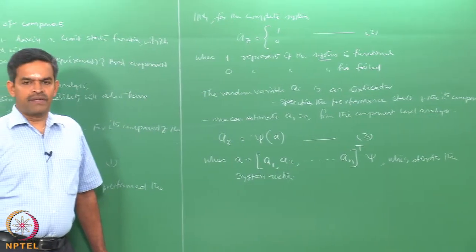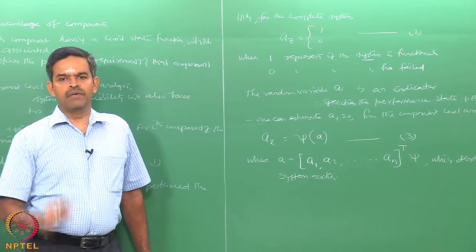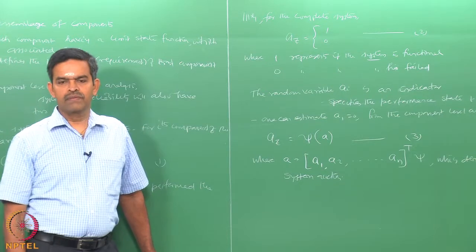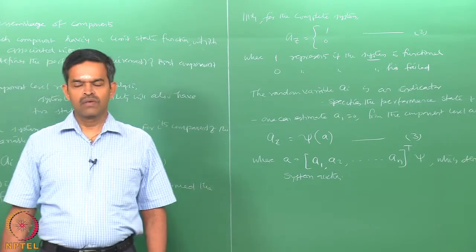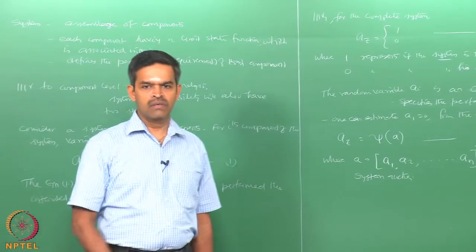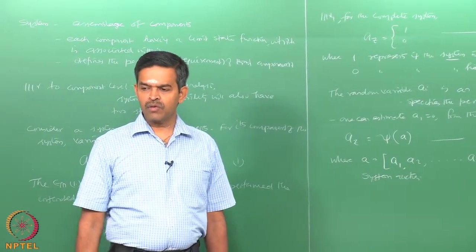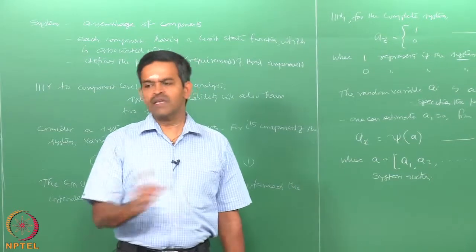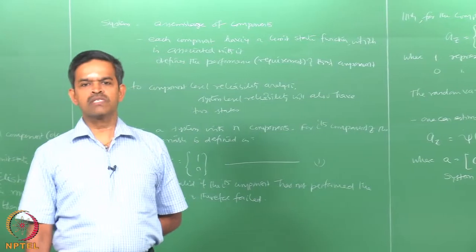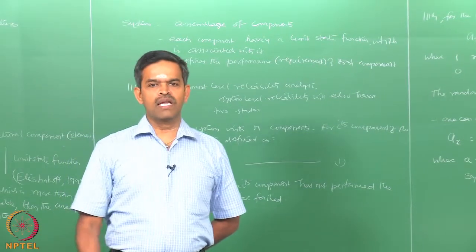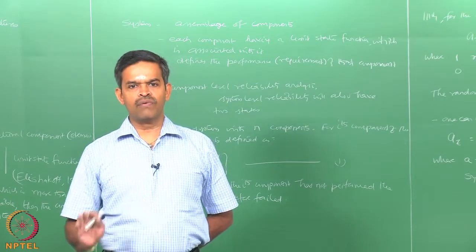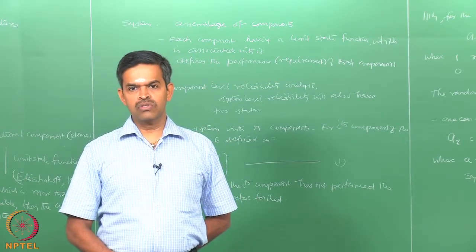While the performance criteria for an individual element is usually easy to determine and fix, you can easily quantify this through a clearly defined simple limit state function. Performance criteria to be fixed for an entire system is generally complex. Therefore, an important step in system reliability analysis is identifying all combinations of the component failure which constitutes the system failure.